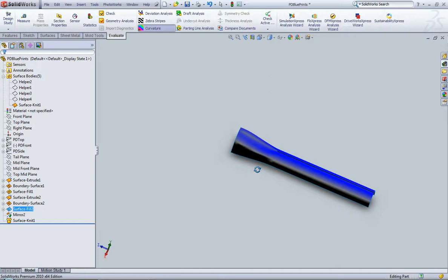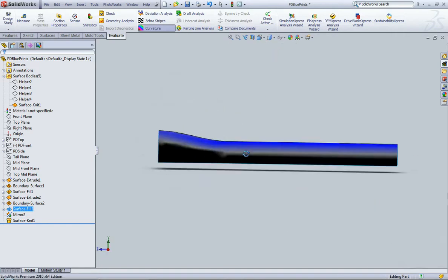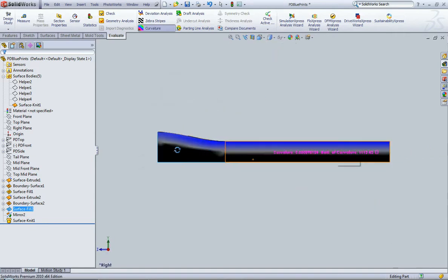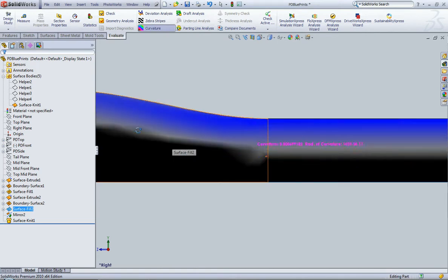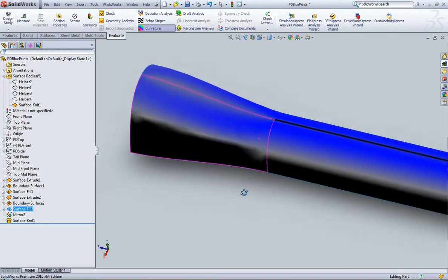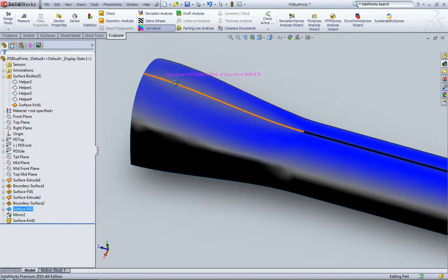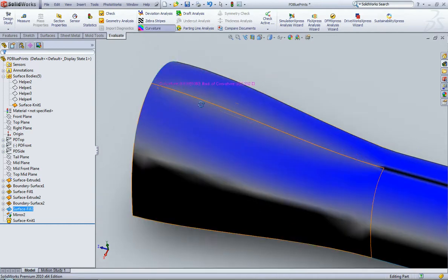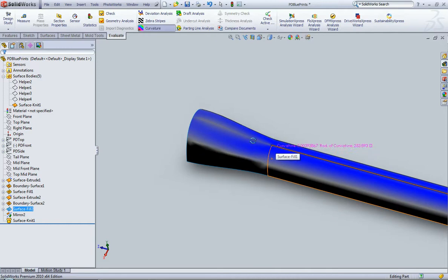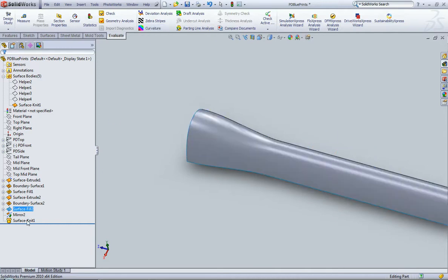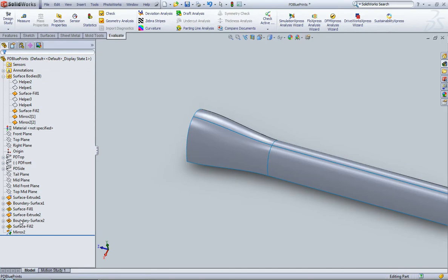and just see what it's telling you, and you really need to understand the results. Now this is obviously not a Class A surface here. The reflections are going to hit this at interesting angles, and up here the transition's probably not ideal because it kind of tapers off here at the end. But in the end, like I said, decide what you want to do with the model, decide what your intent is, and go from there.